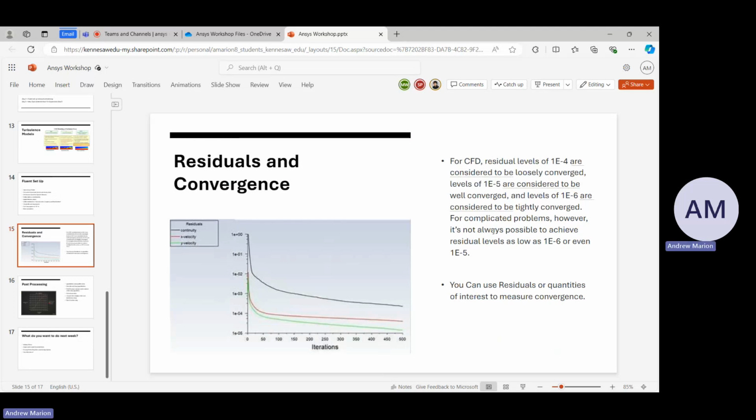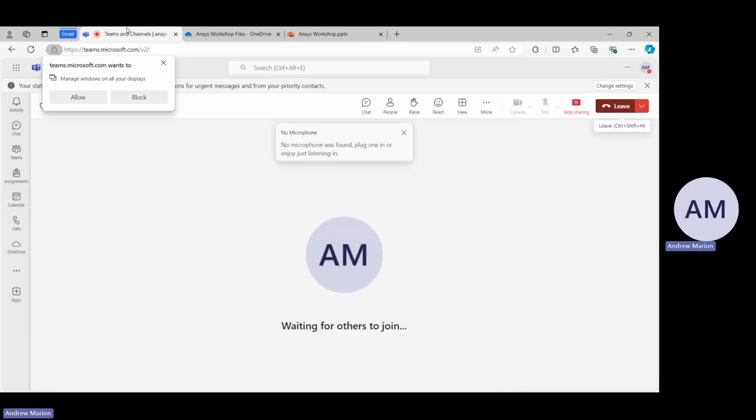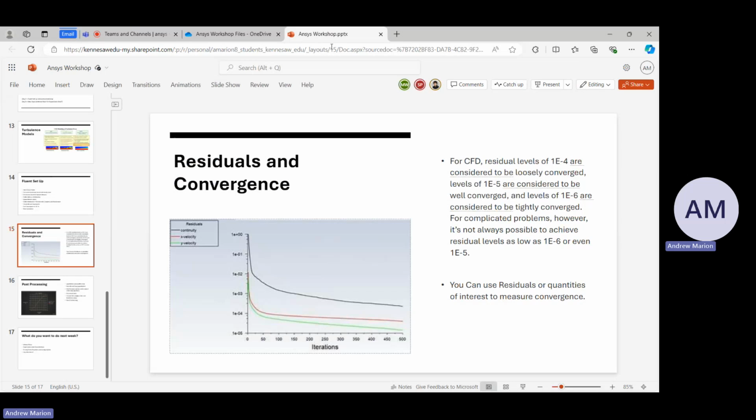The relaxation factors are the constant it multiplies the next value by to give it a difference to try something new. You can increase that factor to make it try a wider variety of inputs, or you can make that factor smaller to narrow the number of things it tries. What works will depend on how the simulation is running.